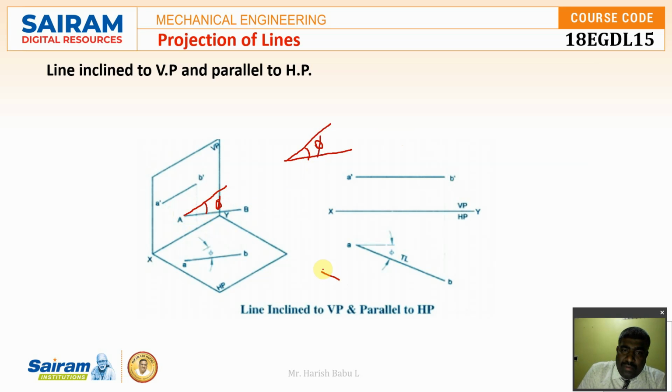So when I want to observe from the front, I can see the length, but I can't justify what exactly the length is, because when I project the endpoints parallelly, the size will be reduced from the actual size. If I assume the actual size is 50, the view size when I observe from there will be reduced, somewhere around 35 to 40. So that length will be reduced. That length is called the apparent length.